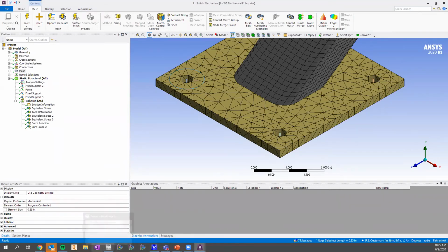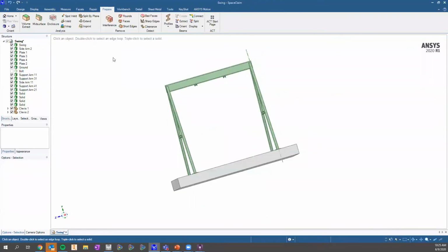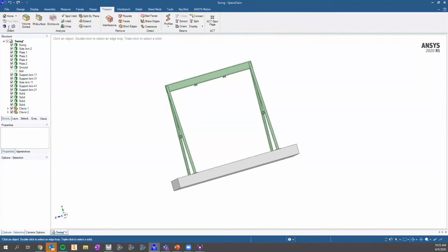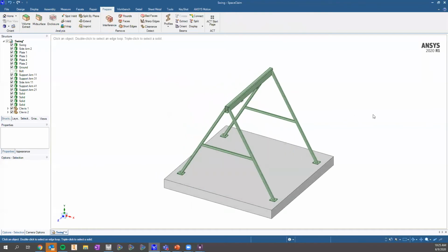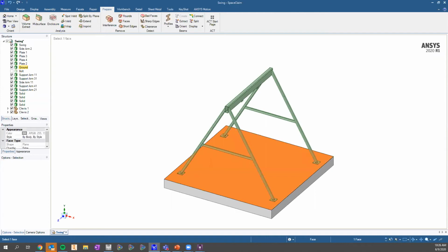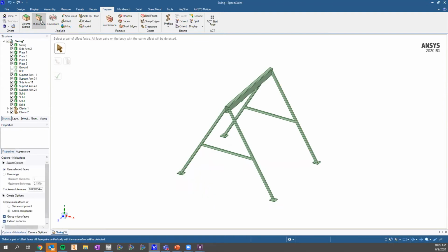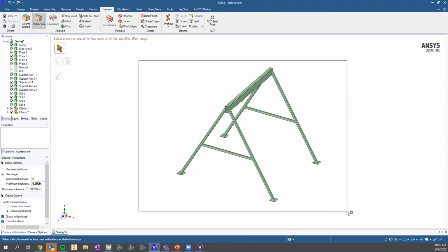Let's use Ansys SpaceClaim. Did it close down? Nope, it's over here. Let's use Ansys SpaceClaim to make shells. Now, this is something that can be very tedious in CAD, and something that we can do pretty rapidly and quickly using Ansys SpaceClaim. I'm going to click on this Midsurface feature over here, and I'm going to use a range. I want to look for plates. I know the thickness of all these tubes on my plate here, 1/4 inch. And I'm going to drag and select.